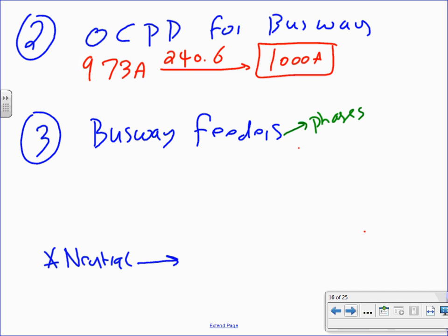Okay, let's go to the feeder. Remember, the plug-in busway is coming up, stopped right here, and then I'm going to put a pull box, or junction box, here, and feed it with a conduit all the way to the switch here. Why would they do something like this, guys? Cheaper. It's cheaper to have the plug-in busway only where the machines are located, right? If you're feeding all these machines from the first floor, and we're on the third floor, does it pay to bring the plug-in busway all the way to the first floor? No, it's a lot of waste of money.